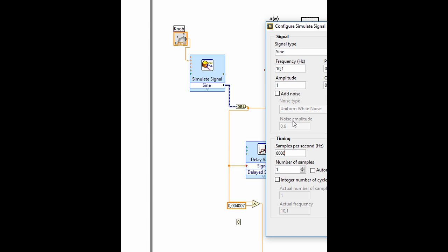But this is how all PCs work. They do not work continuously. They've got a certain speed at which they get one value at a time. So you can either store a lot and then do the calculation, or what makes these finite impulse response filters nice is that as it's measuring the input, it's got enough values that you stored in the past to calculate either the average or the coefficients so that it will make an immediate answer for you. So as it measures now, it's going to give you an immediate answer.